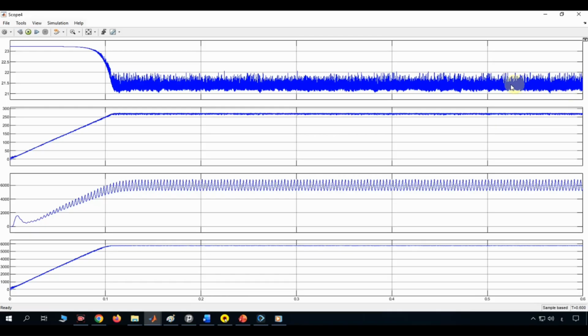Given the scale of this signal and the way it behaves, starting high, dropping once the system finishes its startup ramp, and then carrying constant high-frequency ripple, this looks very much like the array's output current. Early in the simulation, before the voltage has ramped up to its operating point, the array is sitting closer to a short-circuit-like condition, which naturally produces a higher current. As the voltage climbs during startup, the current settles down to its normal operating value, and the continuous fuzzy noise afterward is the electrical ripple caused by the switching action of the power converter feeding on this same current path.